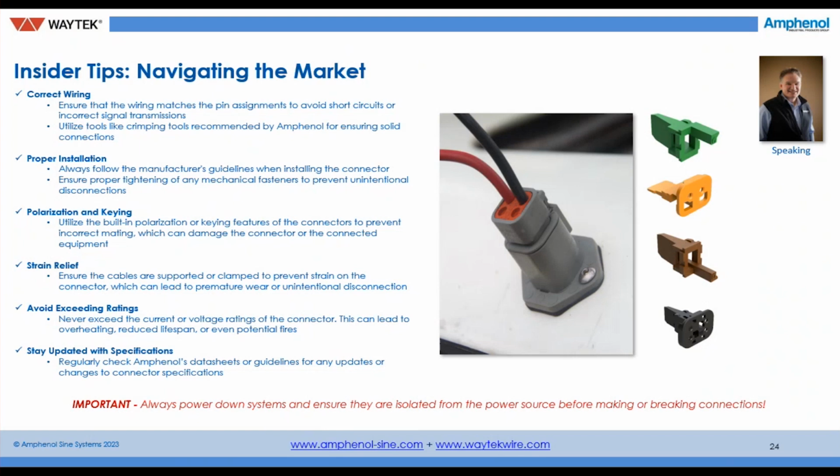That keying is illustrated when you look at the green and the brown. You can see a peg, if you will, or a keying feature that would extend. In other words, if that keying feature doesn't meet with that mating wedge lock to allow acceptance, there is no mateability. So this is one of the great ways that we can take a very cost competitive thermoplastic connector that can work in a wide range of environments, can excel at high IP requirements, vibration, temperature. Here we can use that same basic housing, that footprint, but by using different keying options that we have, we can facilitate the avoidance of mismating.